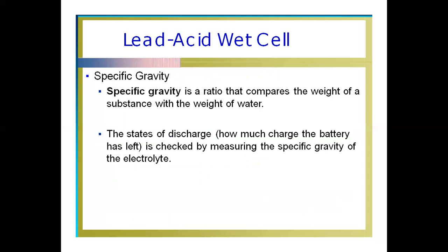The specific gravity is a ratio that compares the weight of a substance with the weight of water. The state of discharge, how much charge the battery has left, is checked by measuring the specific gravity of the electrolyte solution.